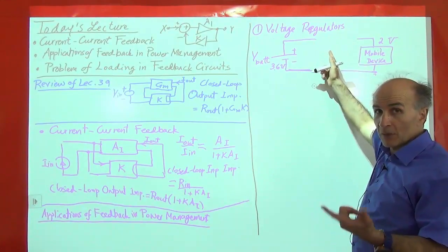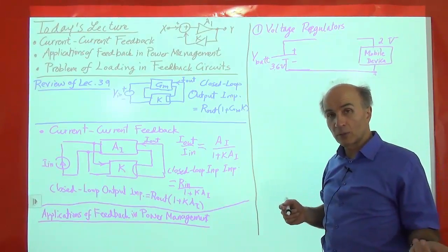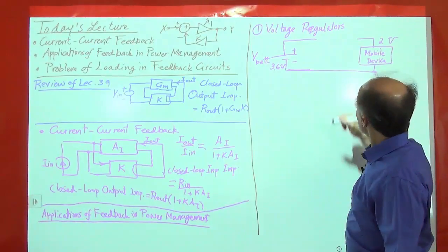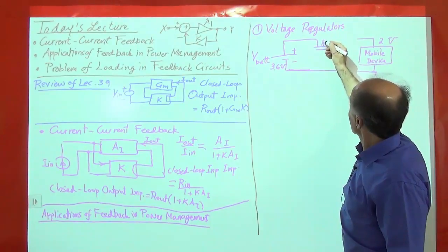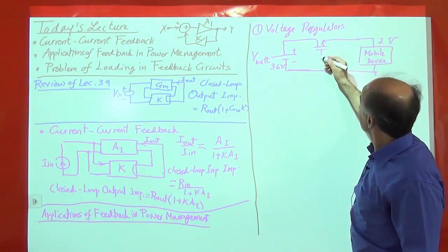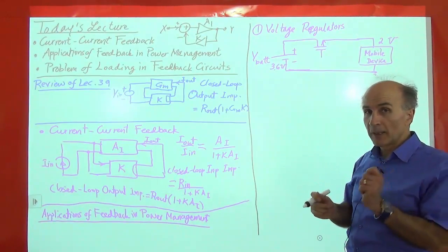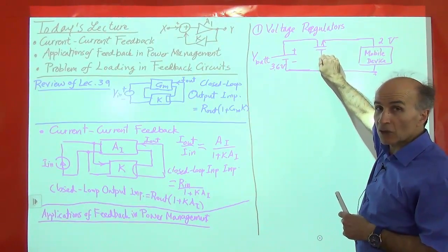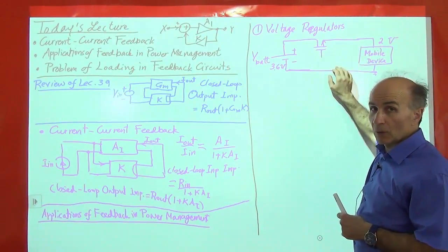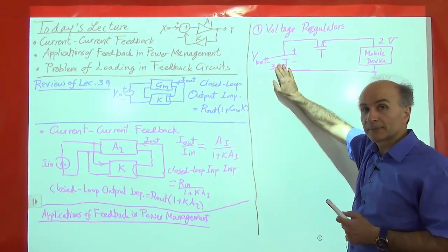It won't work. So it has to be a 3-terminal device. What 3-terminal devices do we know? Transistors. So let's use a MOSFET here, an NMOS, for example. And my hope is that by adjusting this gate voltage, I can make sure that this is always 2 volts, even though this has some changes in it.